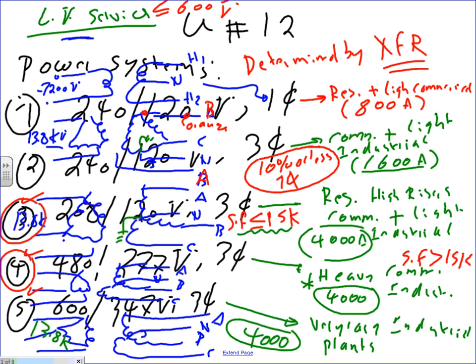The higher the voltage, guys, the better, the more efficient the system is. Everybody knows that? The higher the voltage that you run a building at, the more efficient, more powerful, and more capable the system is. But what's the drawback? The more dangerous the system is. You put 600 volts across two phases in a panel like this and ask Ashley to work on it, you arc flash that panel, you can kill somebody, versus 208/120. So the higher the voltage, the more dangerous, but the higher the voltage is also more efficient.